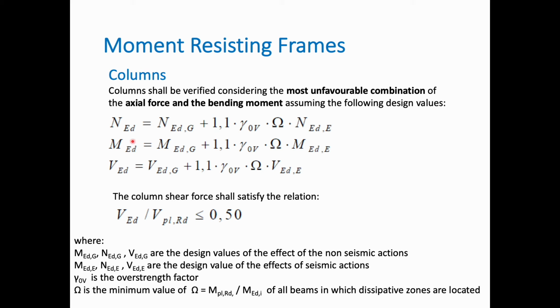For the MEd it is the same thing, so MEd is equal to the MEd,G for the non-seismic actions plus 1.1 times the overstrength factor times omega times MEd,E. And for the VEd, again, the same design value and design formula as before.